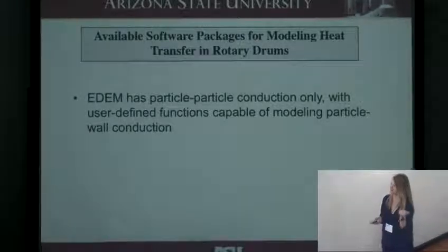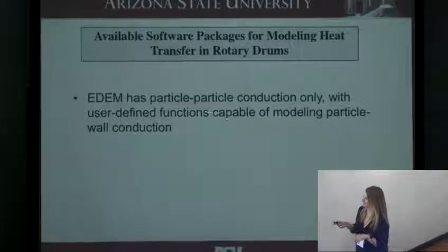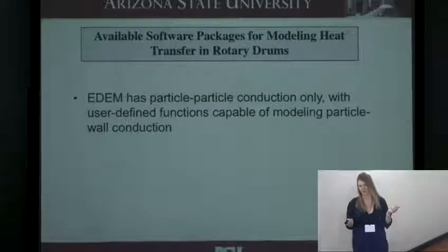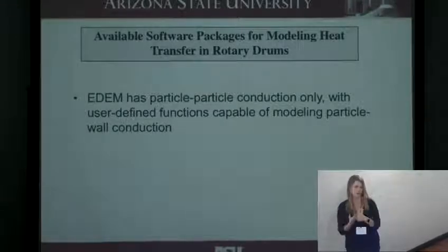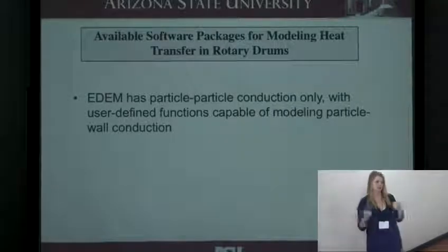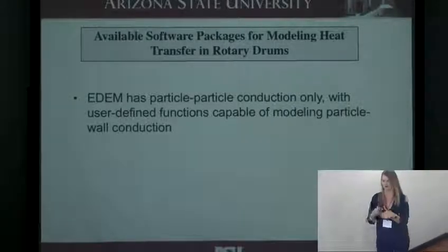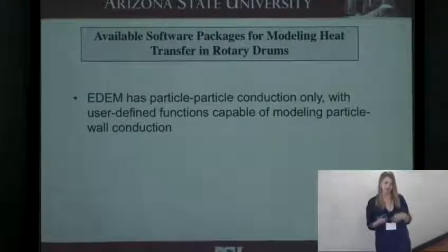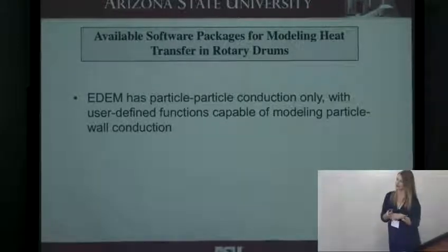It was the easiest to use. It has particle-particle conduction, and then at Rutgers we had our own code to do the particle-wall conduction. But that's basically all you can do since it's just pure particles, so you would have to couple with a CFD solver to do convection.